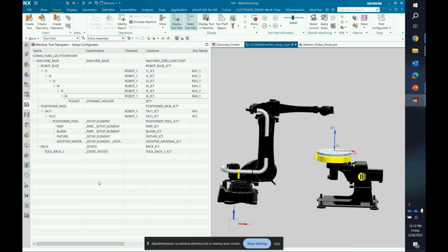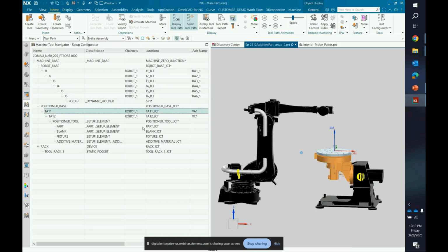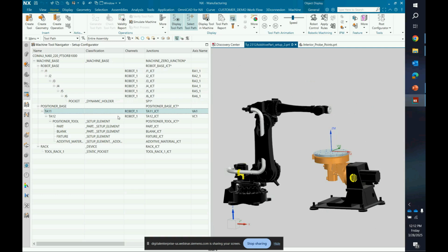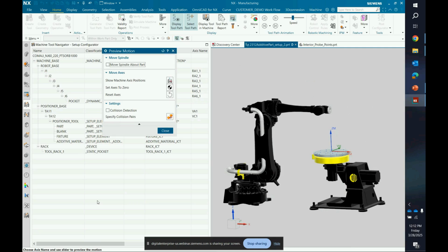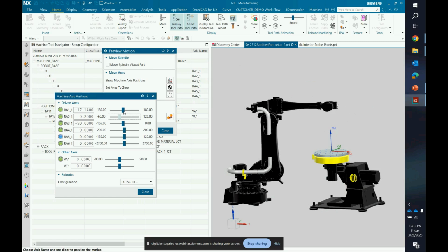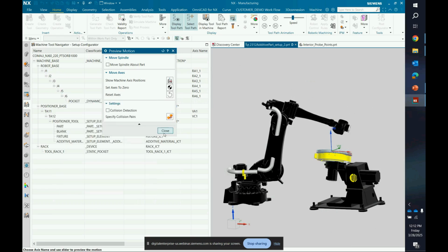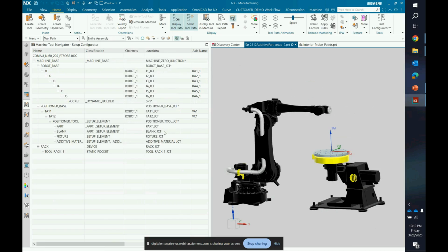Same thing with the positioner. We start defining the rotation point for axis 1 on the positioner versus axis 2. We get this kinematic tree built, and then we can start actually moving this thing around. So now I've taken those graphics and moved them into a kinematic model. And now when I go to simulate, my environment will simulate those tool paths and move how I want it to move, mimicking the physical world.